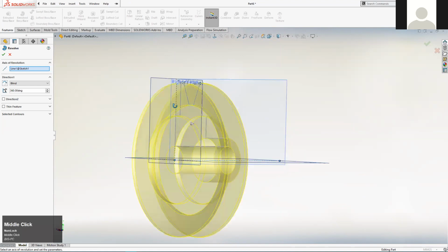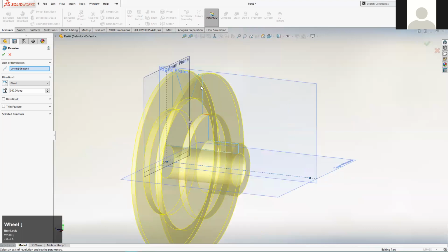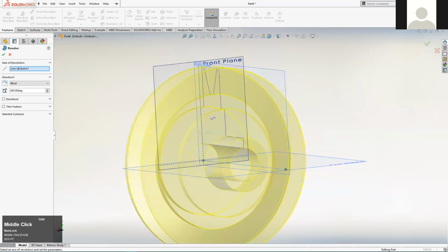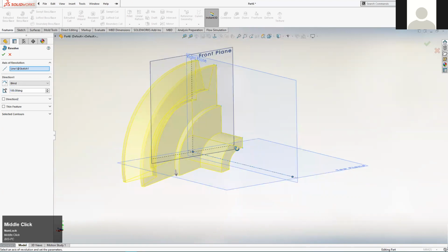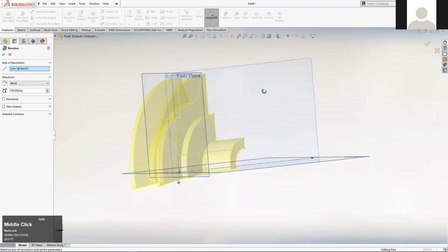But anyway, so we're getting our preview. Preview looks good. We can still see our sketch sandwiched in there. If we wanted to play around with some of these revolve options, we could. So very similar to the extrude options, we have a blind value currently, but rather than in millimeters, it's in terms of degrees round the center axis. Let's say we didn't want a full revolve. Let's change that to 100, and you get that sort of thing going on. So that might be useful if you're designing certain parts.